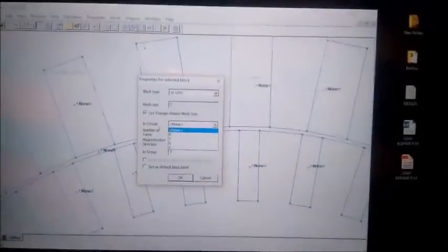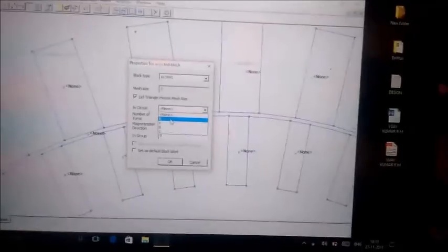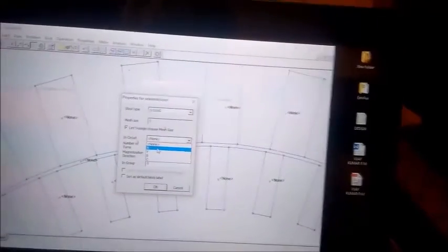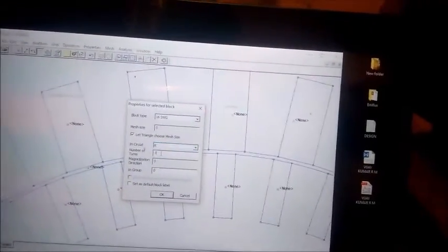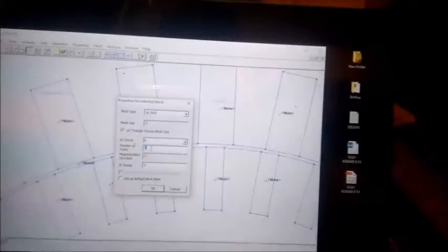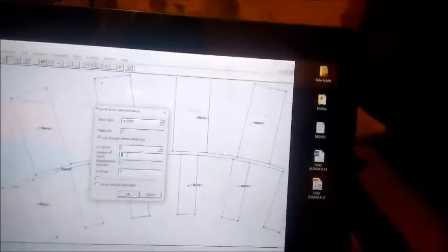You would have calculated the number of slots per pole per phase, so choose the slots which have R and the different ones. Now for series you need to give the number of turns, that is turns in the slot. You will know the conductors per slot, so just divide it by 2. Here I'm taking 2 turns per slot, so click OK.